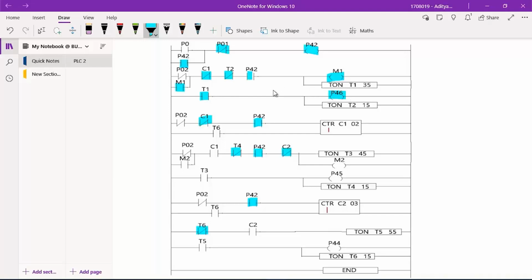Now if you remember, we assumed whenever an object, the first object basically, is sensed by the sensor P2, it takes the object 3.5 seconds to reach the first cylinder. So it means after 3.5 seconds, the object will be pushed by the first cylinder into the bin.